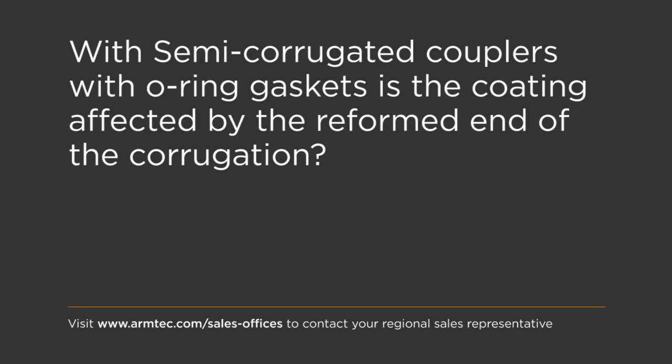Semi-corrugated couplers with O-ring gaskets, is the coating affected by the reformed end of the corrugation? The reformed ends would be painted with the zinc rich paint, as Patrick alluded to. Any damage done to the coating would be touched up with the zinc rich coating. And if it was polymer laminated pipe, that would also be painted with a polymer type paint, or a bituminous paint.